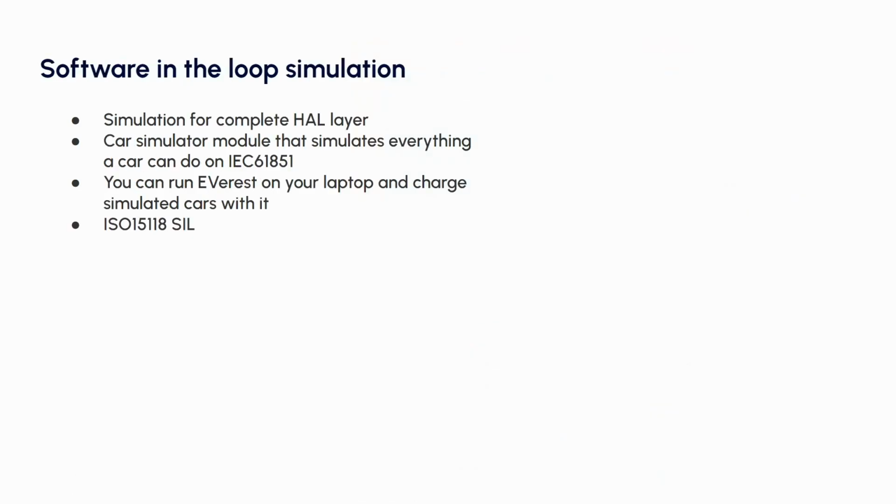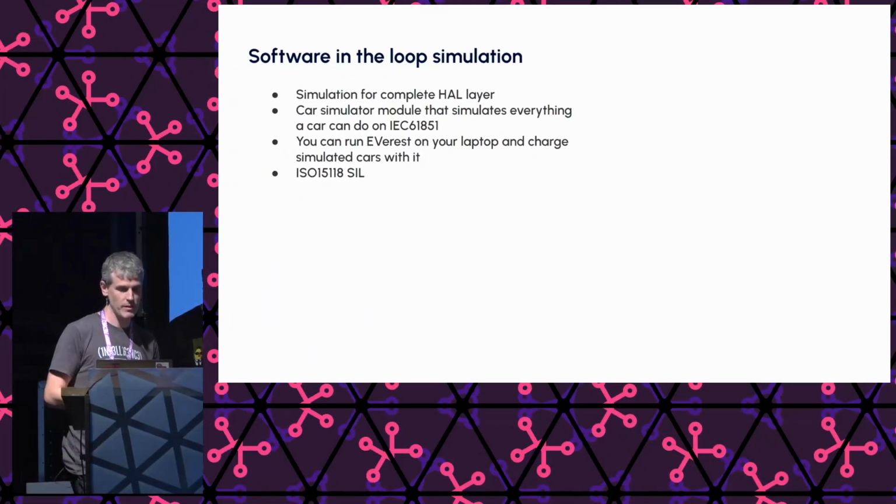What's interesting as well, we have a complete software-in-the-loop simulation, so the hardware abstraction layer I was talking about earlier, for each of the hardware drivers, there's also a software simulation module available, so that basically you can run the whole EVerest stack just on your laptop without any charging station or a car. And you can also load a simulated car module that you can attach to those simulated charging station modules, and you can run full charging sessions, including ISO 15118 support, and basically develop EVerest and run simulations, and can do fully automatic testing, for example.